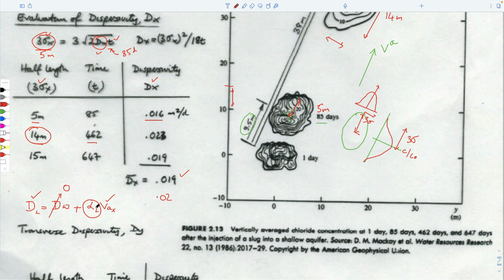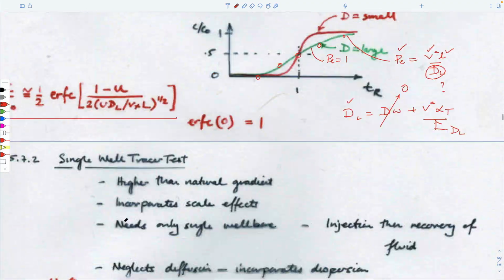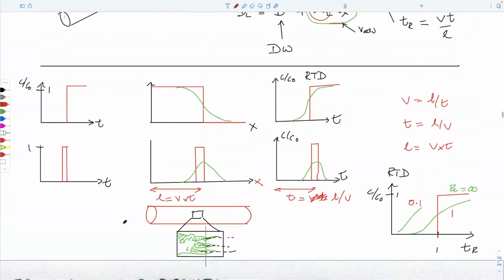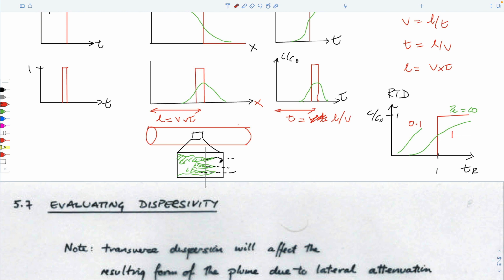And so we're treating that as a fundamental parameter that describes the heterogeneity of our aquifer. If we think that this description that we talked about before, that these superhighways are the reason that we get spreading ahead of the front, is that because we have pristine water in here, we have contaminant traveling ahead of the front in this little lens. On average, it looks like a value which is arriving early because it's ahead of the front. In space, it would be this point here, a low concentration.